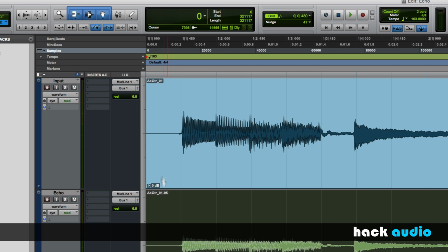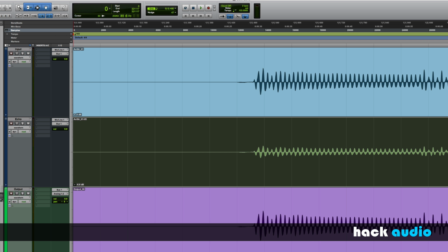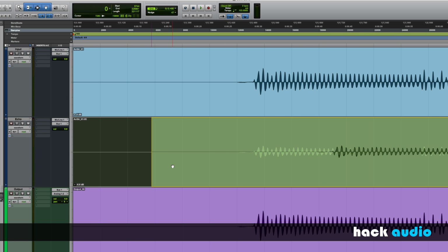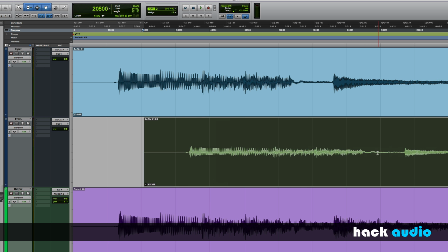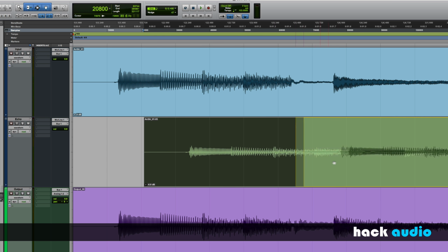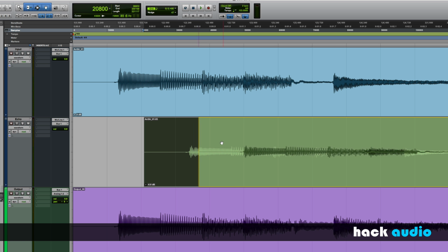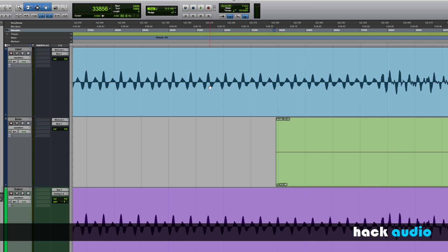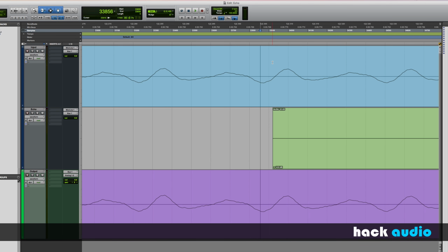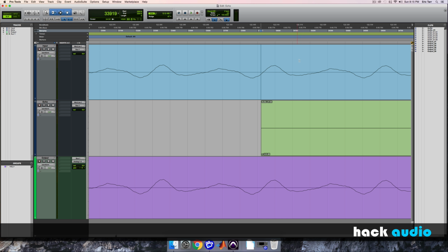So I can switch this over and we can look at what we can do is perform a time delay all the way down to our sample. So we could shift this over, maybe 10,000 samples would be this duration, or maybe 20,000. 22,000 is half a second. We go all the way up to like 44,100 samples. Right about here. So in this case, what's going to occur? We're going to add in maybe something right around 44,100 in our top signal, plus this delayed signal to get our output at sample number 44,100.